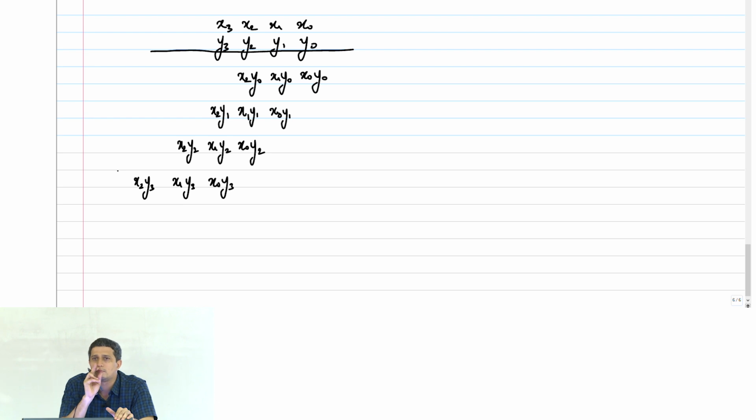How do I make a number negative? You have to take 2's complement of that number, which means you invert them and add 1 to it. So I will invert these numbers. Of course, these were zeros earlier. I am going to now make these 1.